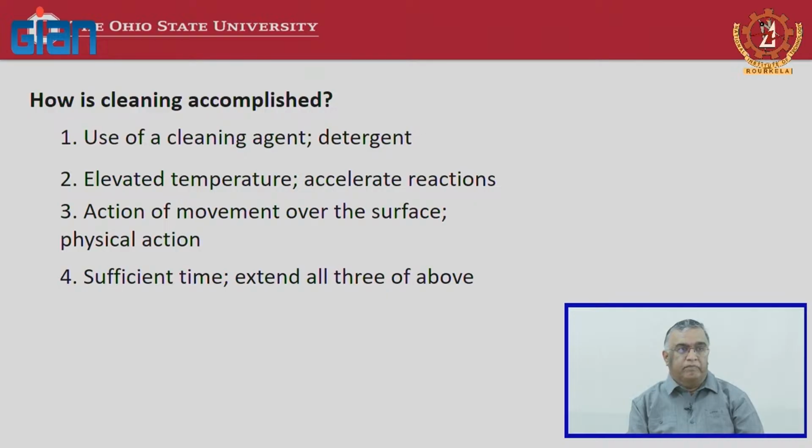And again, when you are cleaning, things may be attached to the surface, so just rinsing water through may not remove everything. So, you need some type of mechanical action, using a brush or other means, so that you can remove it better. You also need to do this for sufficient time, to make sure all the foulant, microorganisms, and other things are removed to the extent possible as part of the cleaning process.